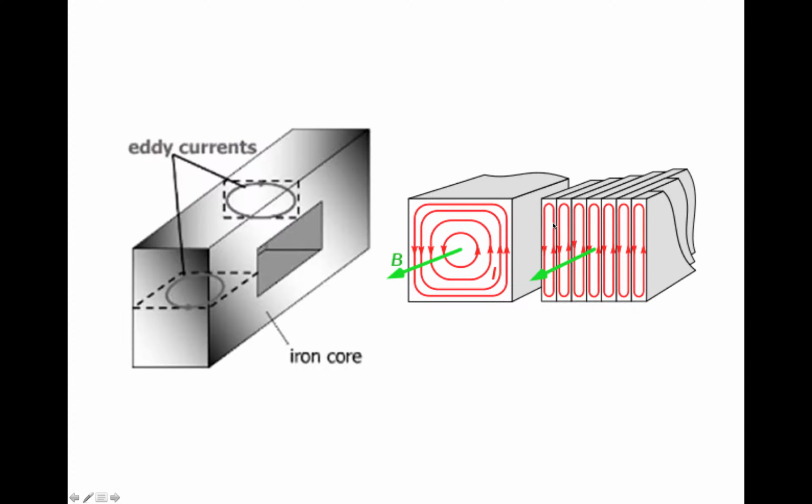What I was just saying is that the strength of the eddy current is proportional to the amount of magnetic flux that goes through it, right? So if you make the area enclosed by the circle very, very small, then the amount of flux that goes through it is very small. So the induced eddy current strength is going to be very small. So that's what people do to reduce eddy current losses. They stack the transformer core by using lots of very thin insulated laminations.